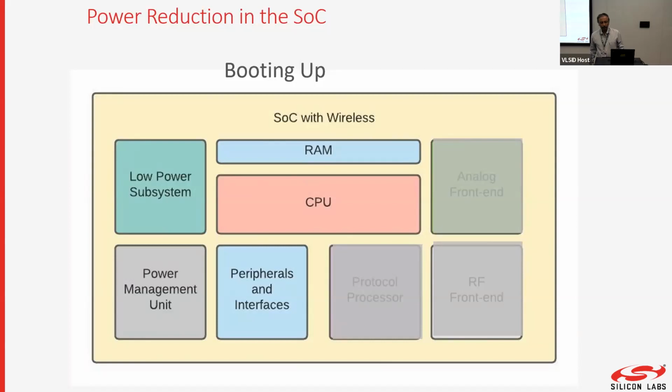Do you have dynamic voltage scaling implemented inside the microcontroller? Yes, it's part of the SoC. So you can have voltage scaling. It's not within the microcontroller itself. You have to look at an SoC version of it. And you can have peripherals which are 1.8 volts or 3.3 volts. Some of them are hidden from you.